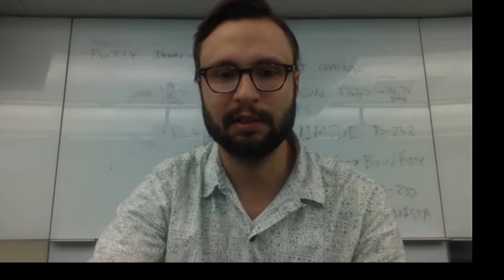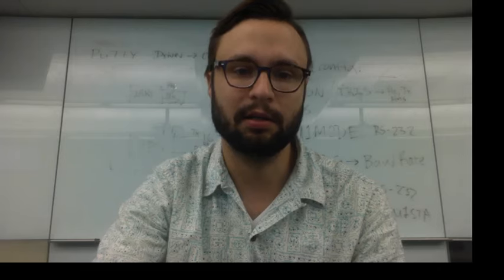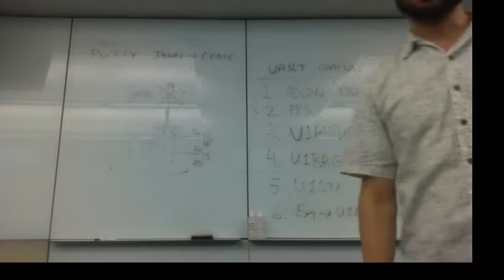then we're popping, but instead of using the pop instruction, they are using W15 directly and the move instruction. Yep. So, I'm guessing the push is equivalent to that move.d, whatever pushing it into it, makes sense. Now, is it because it's that D, or is that double? Yeah, move.d moves 2 words at the same time, so I'm not sure.